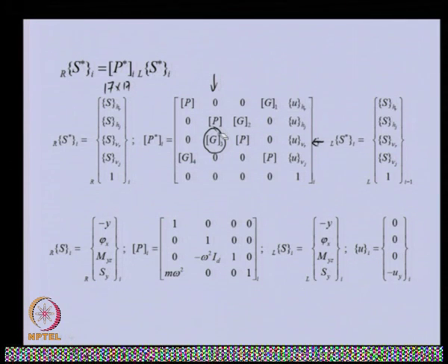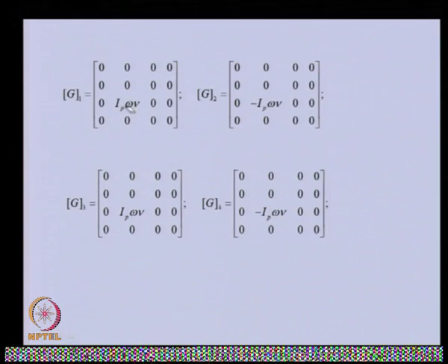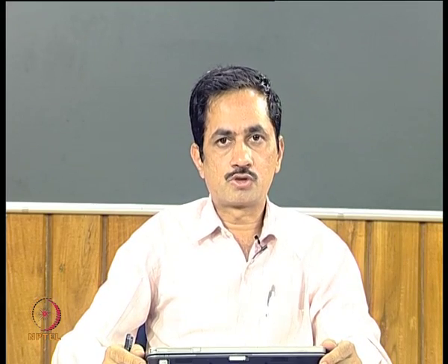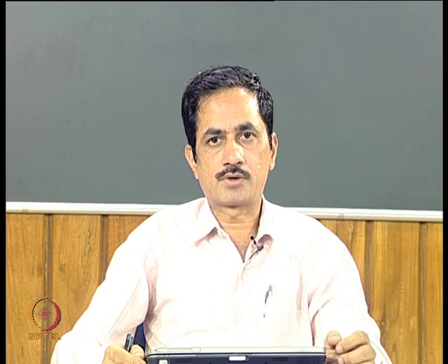And in this particular case, you can see the G is this one, in which omega is the spin speed of the shaft, nu is the whirl frequency, that is the natural frequency of the shaft, and now both whirl frequency and the natural frequencies are appearing. That means natural frequency will now depend upon the spin speed of the shaft, that we already saw in the gyroscopic effect when we discussed that particular topic in detail. So, we have seen the derivation of the gyroscopic effect, how the point matrix gets affected with that.